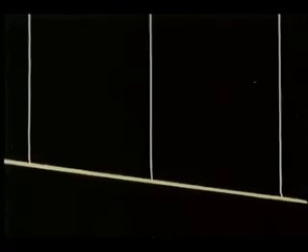To see why a turbulent boundary layer can withstand a larger unfavorable pressure gradient without separating, we shall again examine the flow along a flat plate. The boundary layer on the bottom side is laminar and two-dimensional. On the top side, the boundary layer has been tripped by a wire placed well upstream. Unsteady motions in the turbulent boundary layer are three-dimensional. Some of the motions are perpendicular to the plane of view.